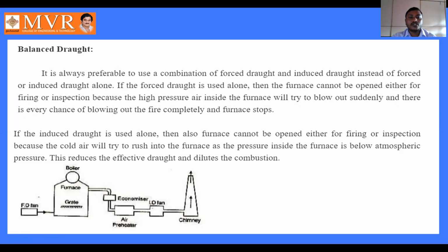If the induced draft is used alone, then also the furnace cannot be opened either for firing or inspection, because cold air will try to rush into the furnace as the pressure inside the furnace is below atmospheric pressure. This reduces the effective draft and dilutes the combustion.